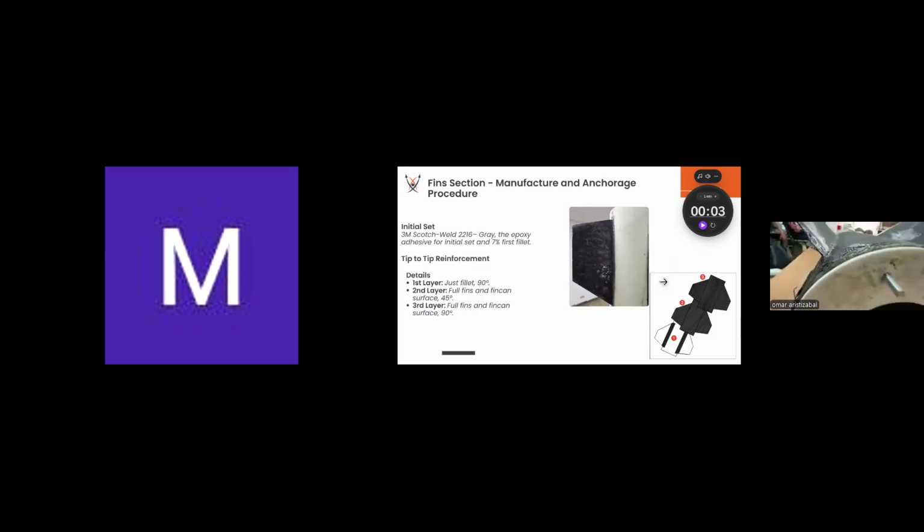And are these fins through the wall or no? They are surface mounted. Okay, but you're doing tip to tip fiberglass? Yep, that's exactly what we did here. Or carbon fiber. Yeah, carbon fiber tip to tip reinforcement, which you can see here on camera. We did three layers.